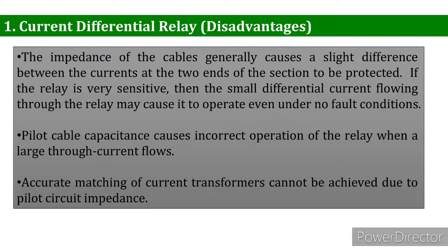In this condition, if we have cables of long length, the impedance of the cable varies, and through that difference we have serious concerns on our current flow, and that may operate the relay even in no fault condition.